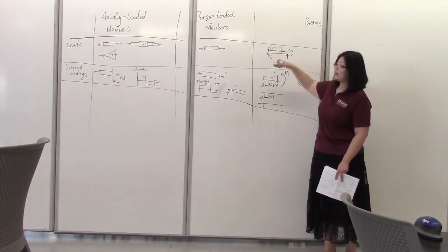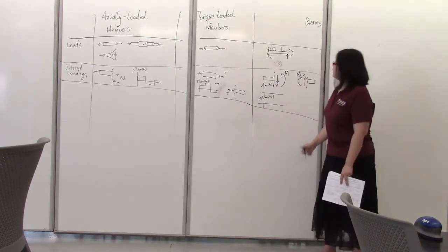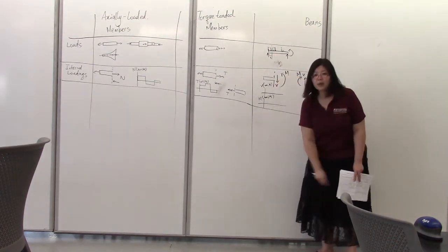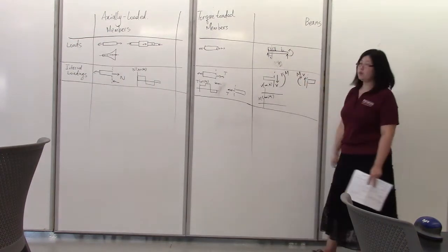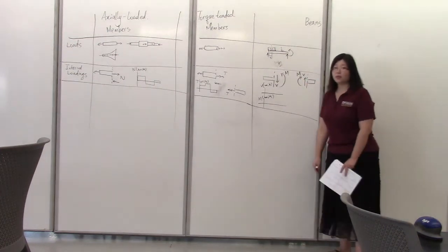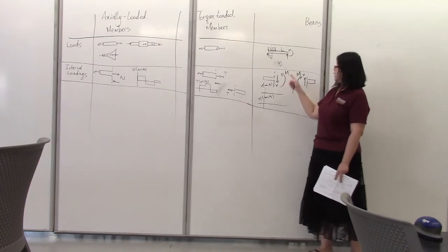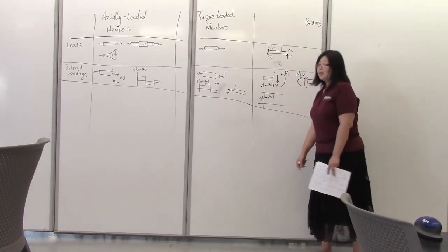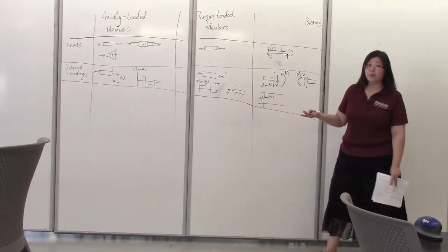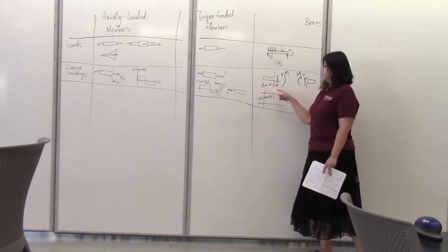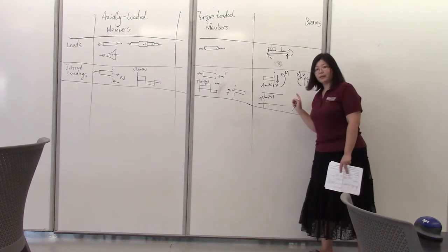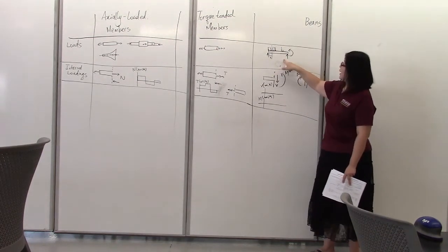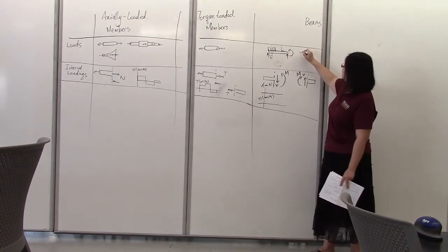Okay, so you make a cut at a generic X location, and then you draw a free body diagram of either the entire left portion from the cut or the entire right portion of the cut. Then you use equations of equilibrium to obtain V and M on the cut section as functions of X. Then once you have the functions obtained, you could plot them basically. So in this specific load case, we would have three different